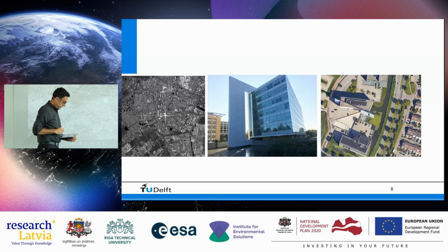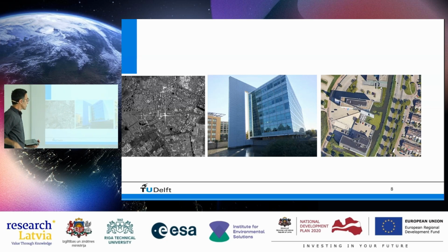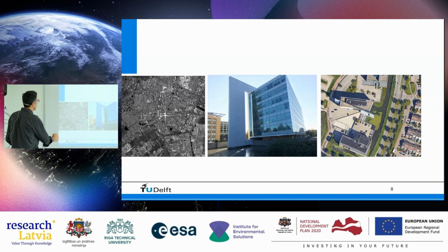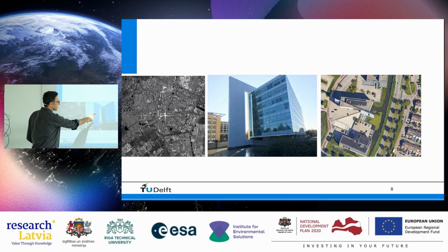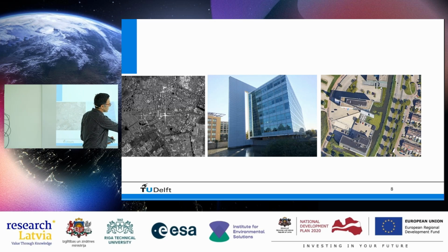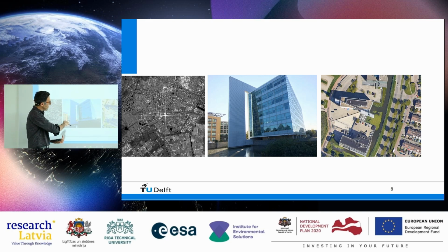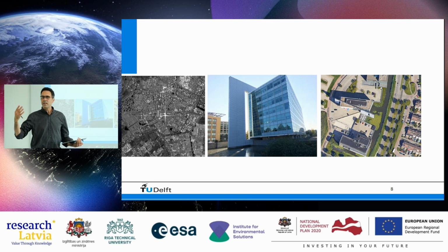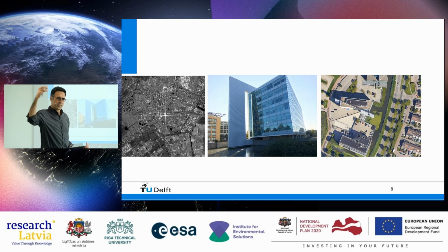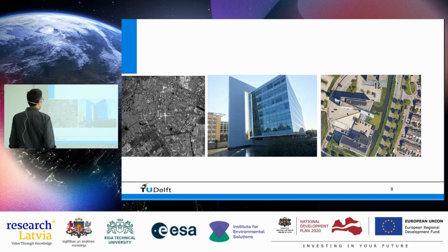And if we want to know what it is, I went there. It was very close to where I live, so I biked over there. And this big reflection is this building. So it's a peculiar building. You see it from the top here because it has this kind of side thing here, and it has a couple of very straight planes, and it has a water level in front. So basically it acts like a very big corner reflector, right? So the radar signal hits the wall, it hits the other wall, it hits the water, and it goes back. So this is why it's so extremely strong in the image.